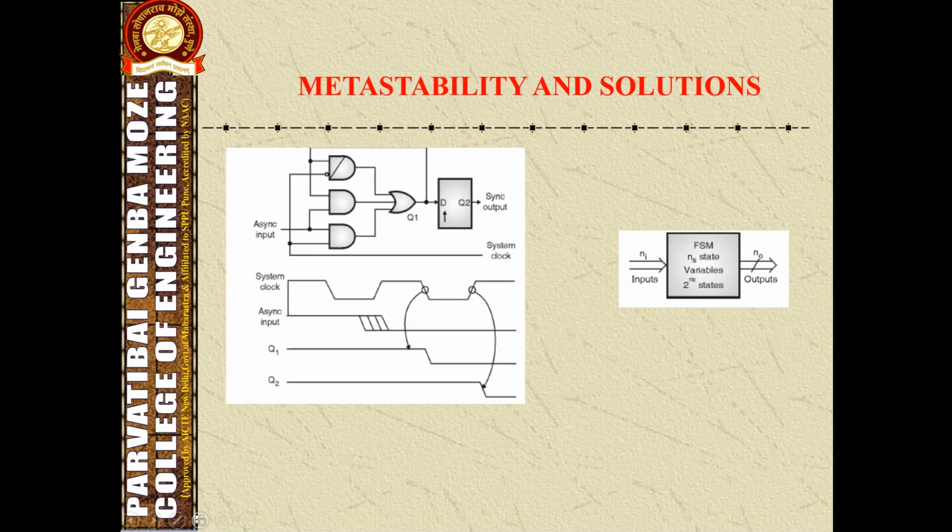Thus, the latch holds Q1 stable to assure the setup time requirement of the subsequent flip-flop, which accepts data on the next rising system clock edge. Similar to a two-stage synchronizer, the probability that the data goes metastable is the multiplication of the two probabilities of each synchronizer.